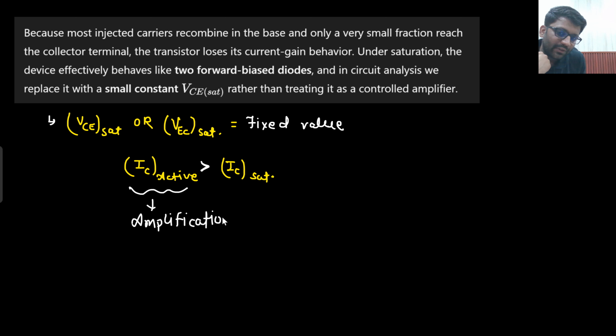So all these things in analog electronics, I will tell you that your BJT for amplification will be used in active region. Why in active region? You have understood here, right? Because in active region, this was the scenario. But here, this is not the scenario. So BJT in saturation region, why do you use it? As a switch. It can be used as a switch.